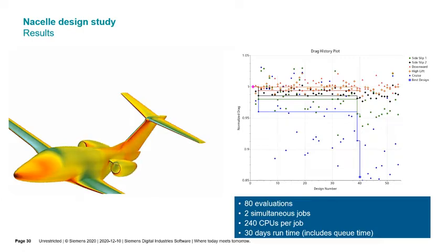If we look at the drag for the other operating conditions, we see that all of them are below the value of 1. In a couple of cases, like the downward and the high lift operating conditions, they are very, very close to 1. So nominally, maybe we just managed to maintain the exact same performance as the baseline design, but the other 3 all managed to see improvements. And I should comment that there is no guarantee when you use a weighted sum of multiple objectives approach like this that you will see improvement in all of your objectives for your best design. It's entirely possible that based on the weighting that you assigned, this substantial improvement that we see in the cruise drag objective could more than compensate for a slight increase in drag, for example, in one of the other less significant operating conditions.